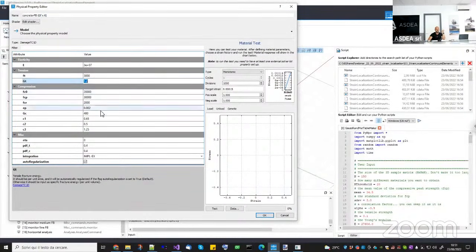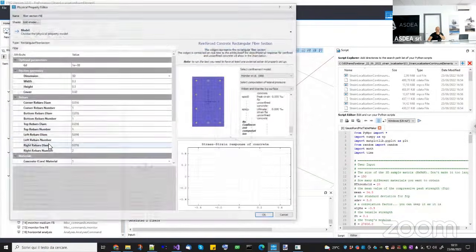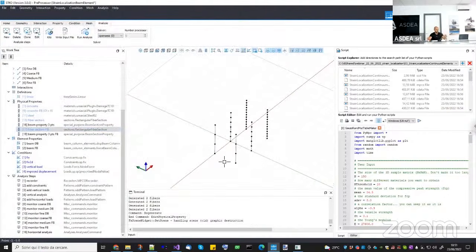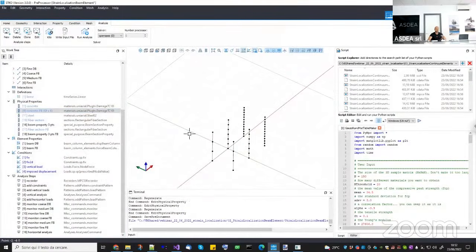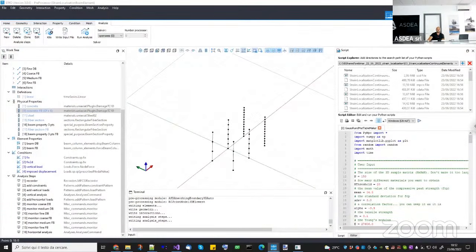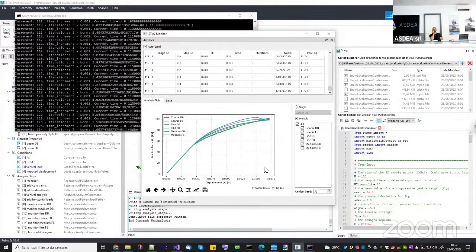You multiply the GT and GC by 6, and then the fiber section for the force-based will have the modified material: concrete for force-based. I simply have to do this, and both of them should be automatically regularized. Automatic, and automatic also here. Perfect. And now I can run the analysis, and let's see if I manage to fix this problem.